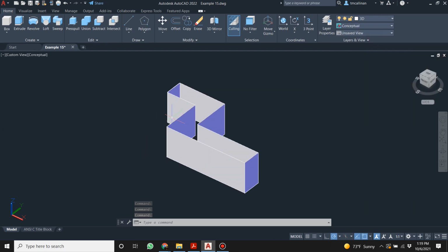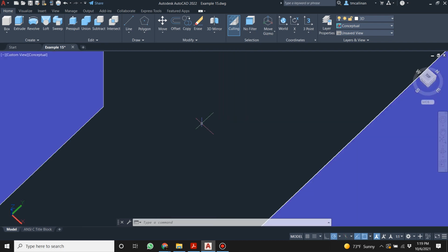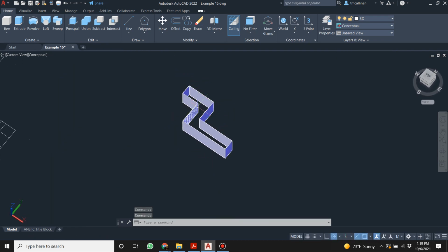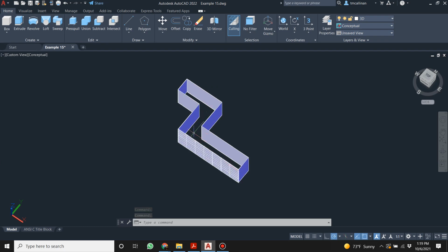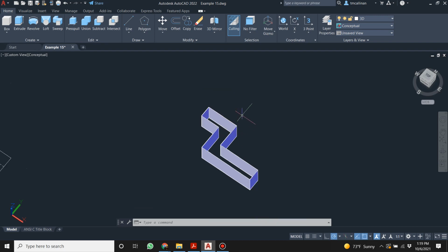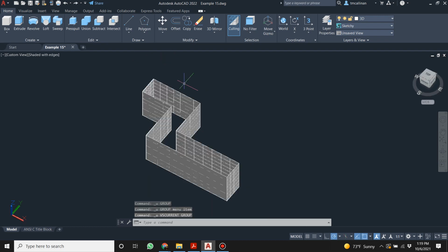Now, I made a mistake and I did it on purpose, but I'm looking for another button here. What's happening here is it did extrude. It basically extruded all the lines, but I can drive right through this. There's a big massive hole going in my part. I needed to make a region. What I want is I want this to be a solid object. What we're doing is we're just extruding the walls. We don't want that. I don't know this AutoCAD. I'm going to press Control Z, and I'm going to undo all of this.